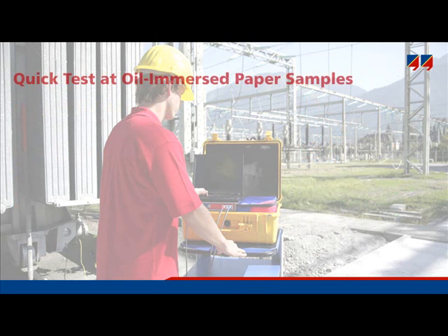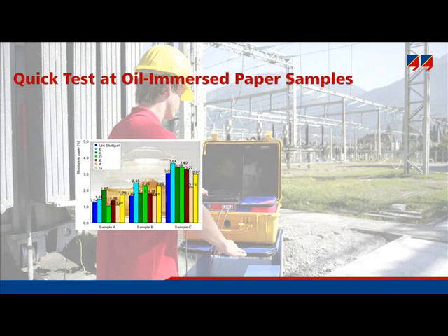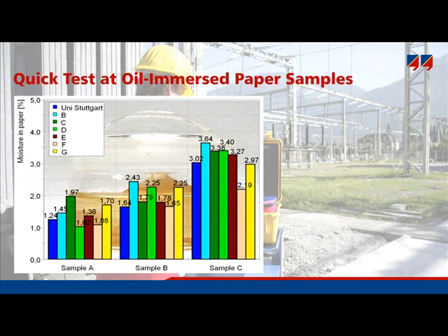The following quick test illustrates graphically how reliable or even unreliable the Karl Fischer titration method is. What has been done? 3 samples of oil-immersed paper were sent to 7 laboratories. The bar graph compares the moisture content in the 3 samples as obtained by the laboratories. In an ideal case, all 7 laboratories would produce results showing the same moisture content. But will they? First, looking at sample A on the left-hand side. Here results were from 1 to 2%. For a further wet sample, the results ranged between 2.2 to 3.6%.